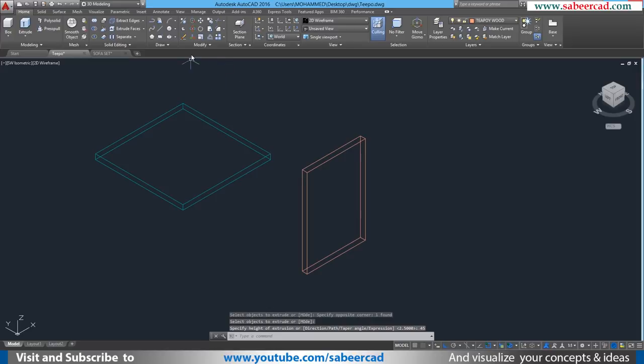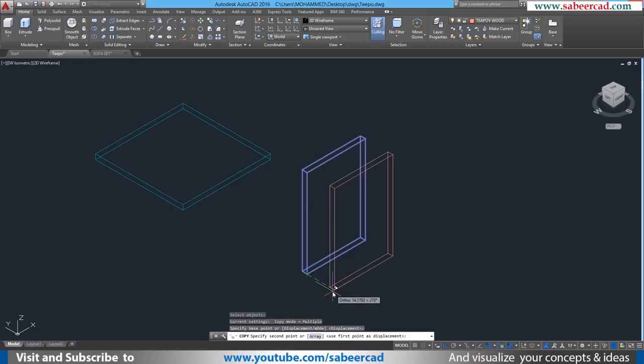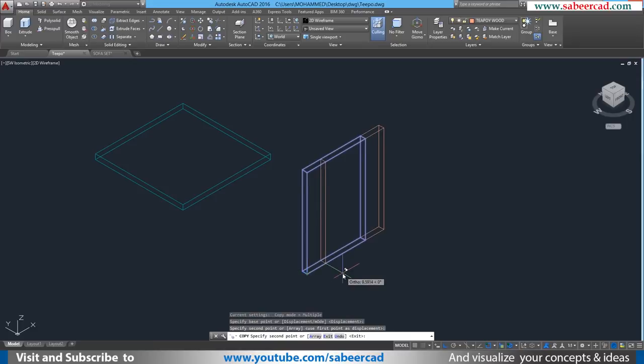And then I'll go to copy command and I'll select this object as the object to be copied. Then I'll right click to give an enter. When I'm asked to select the base point, I'll just pick this point as a base point. When I'm asked to give the second point, I'll pick the same point. And I'll just give an enter to go out of the copy command. Now I have got a coincident copy of this object over itself.